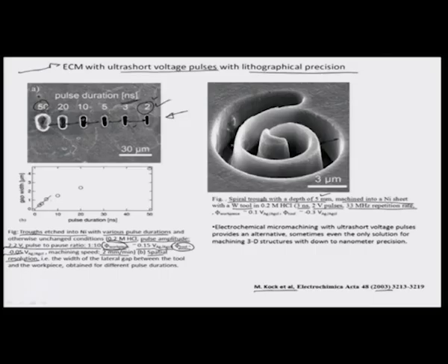So, they are for the first time introducing a high voltage pulsation to see what the finishing aspect is associated with such a high voltage pulsation. The workpiece potential in this case is 0.1 volts with respect to an AgCl electrode, and the tool potential is calibrated as minus 0.3 volts with respect to an AgCl electrode.